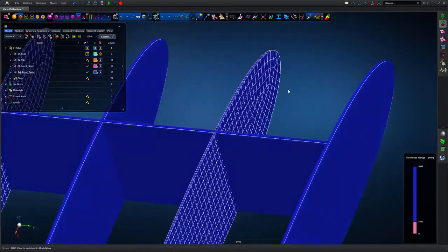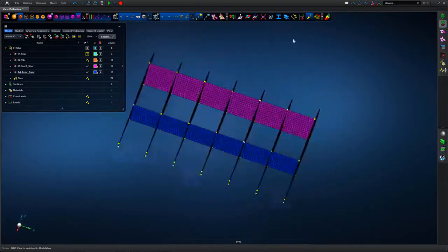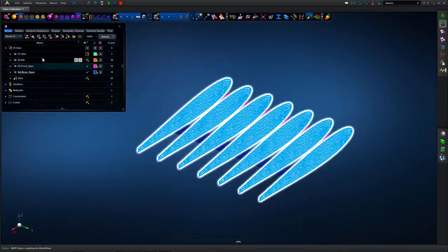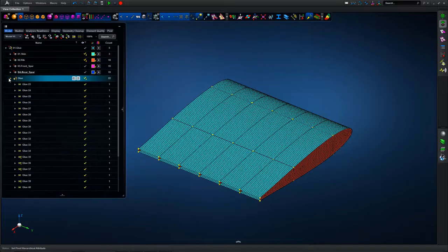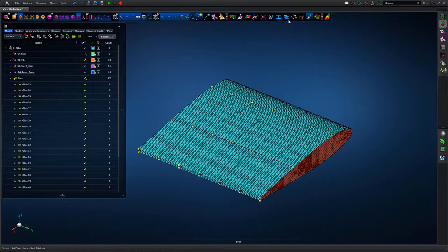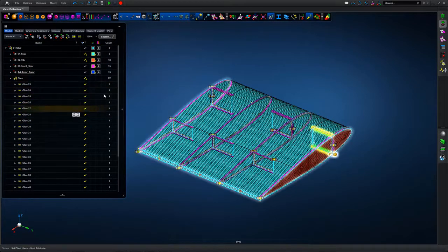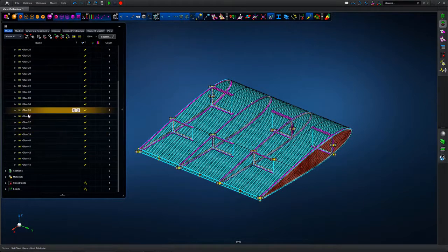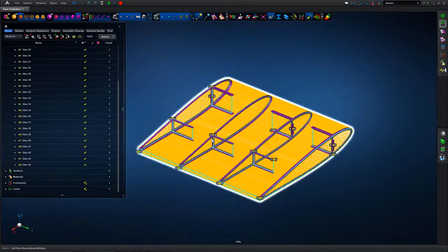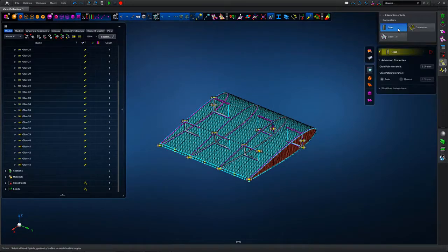And again, if we look at the 3D thickness plot, you can see the way that the surfaces abut one another in a similar manner to how we looked at for the original rib layout definition. So just viewing some of the glue patches, we can see here, because we've split the front and rear spars, we have now lost some of the glue contact definition from those new cuts within the spars onto the wing skin and the ribs.